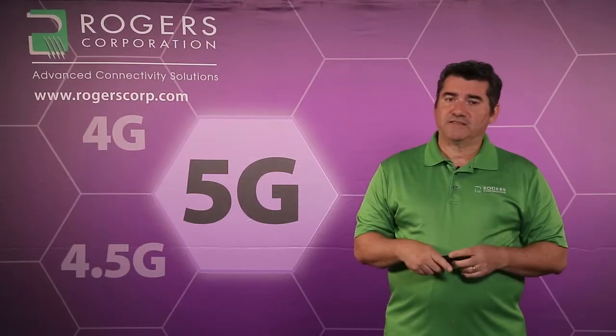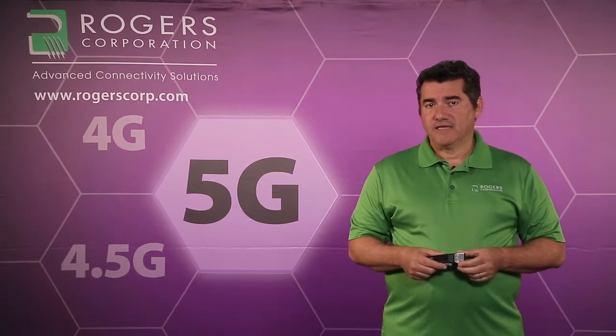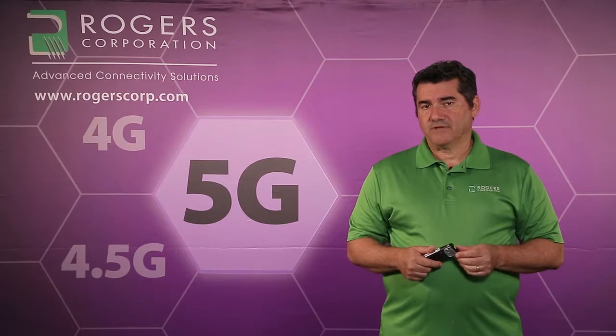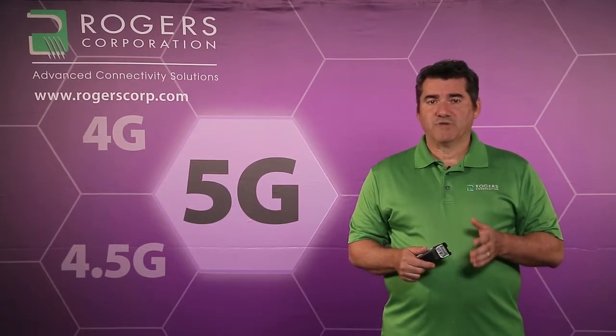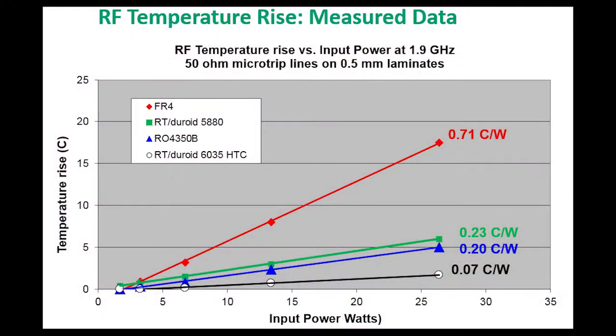So all that was calculated data. Now the important thing is, what are the actual measured values? In the end, when we sit down to make the selection, we want to have our values based on what we measured versus what we calculated. And that is what this next chart will show. Here we have actual measured data of various materials from Rogers: RT-Duroid 6035 HTC, the RO4350B, and the RT-Duroid 5880. And for comparison, we also have in there some traditional FR4 materials, epoxy glass.